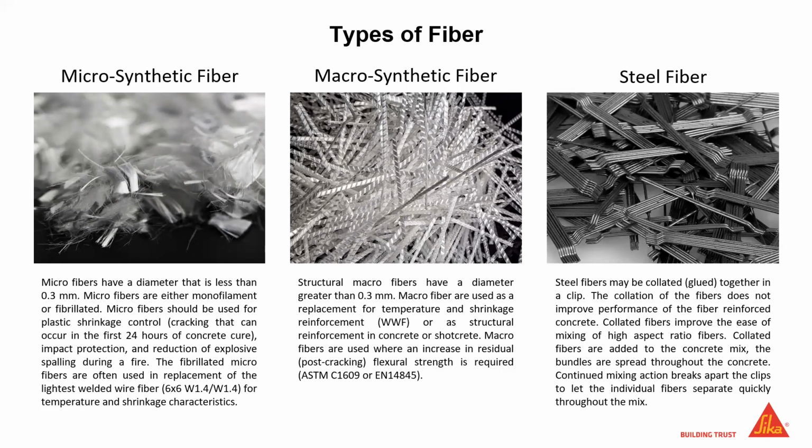There's micro synthetic fiber that you see there on the left. In the middle, you see the macro synthetic fiber. Again, you're getting into what we refer to as a structural fiber, and I'm sure you're all familiar. Everybody seems to be familiar with steel fiber if they're familiar with any macro fiber. Both the macro synthetic fiber and the steel fiber are considered macro fibers.